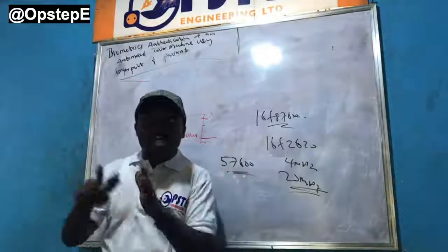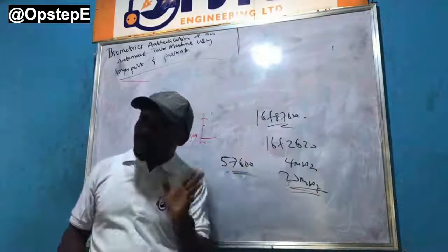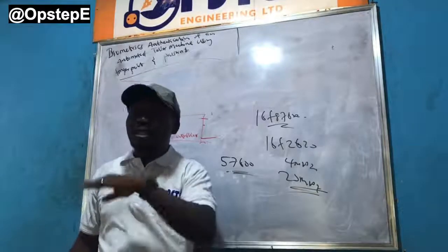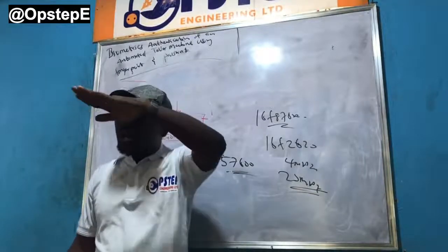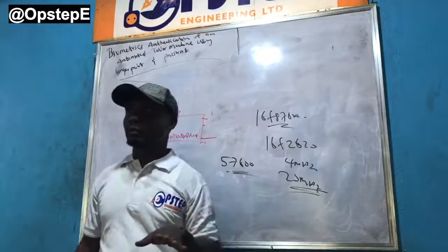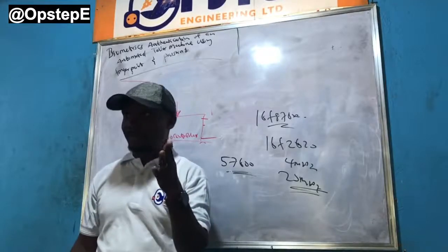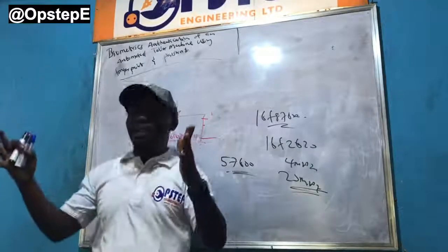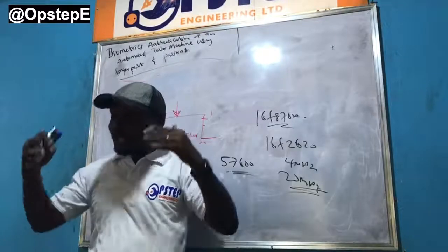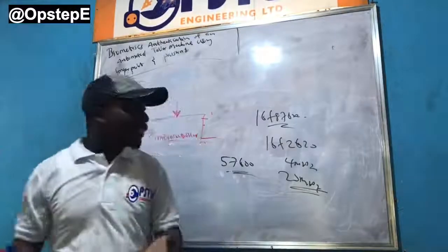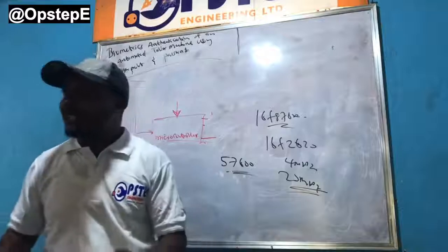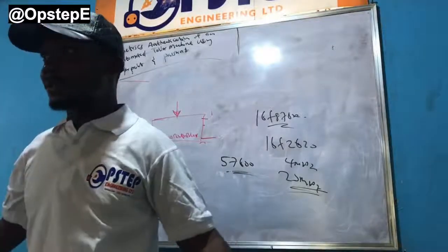See that relationship? The same relationship the baud rate has with the crystal you are using. Based on the crystal you are using, there are some values you cannot go above. So what do you do? You increase the crystal. Then you have some other boundaries you cannot exceed, or values you cannot use. Then you increase the crystal. But the issue is that even the microcontroller cannot allow you to increase the crystal more than 20 megahertz.